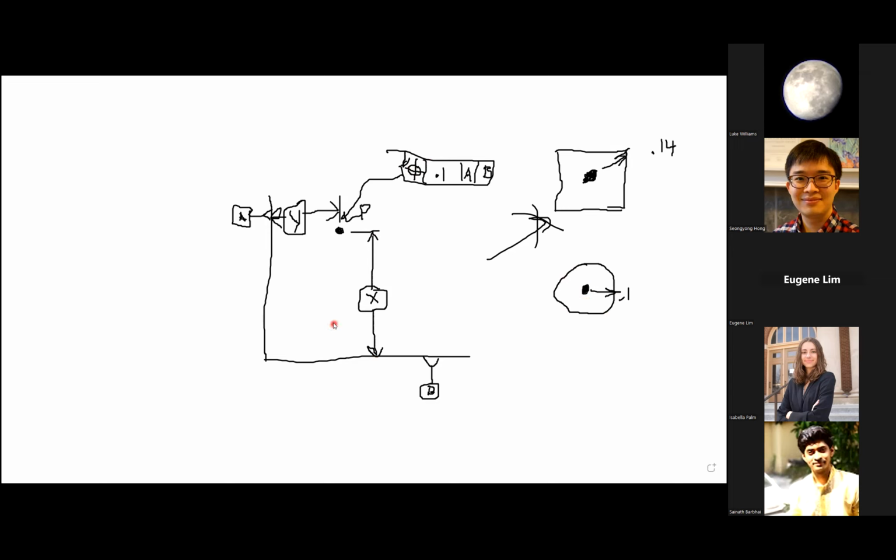And so it's a great way to give a clear communication from designer to manufacturer exactly what you're looking for. And it does it in a way that prevents a compounding of tolerance errors like we have here. So that's sort of the main thing with control features and datums and all things GD&T.